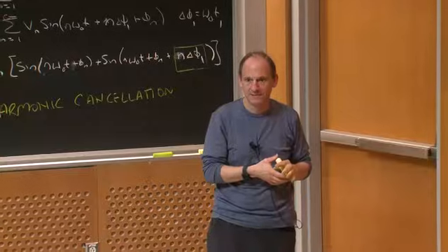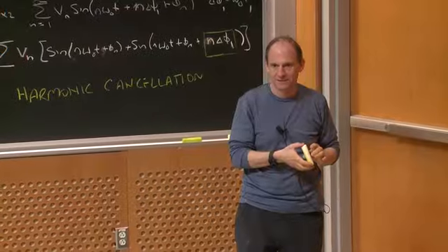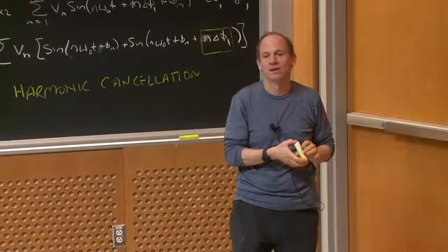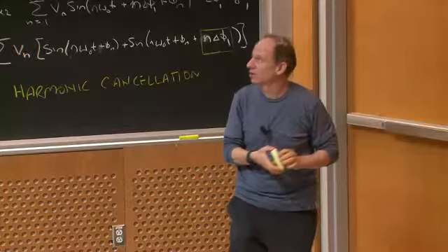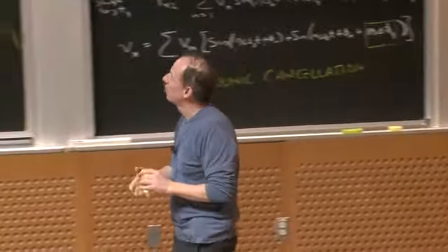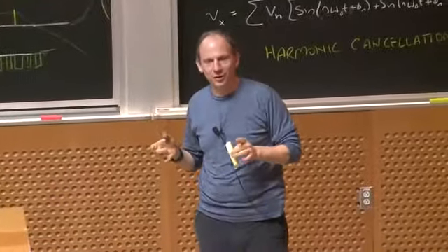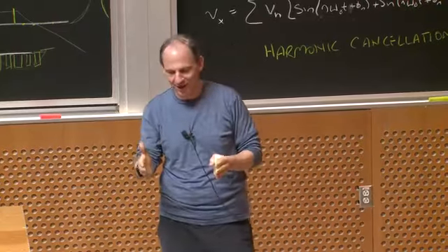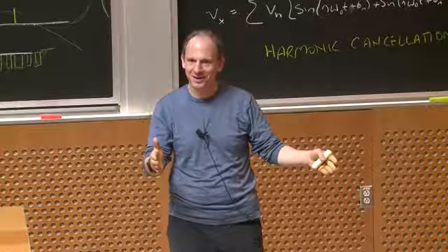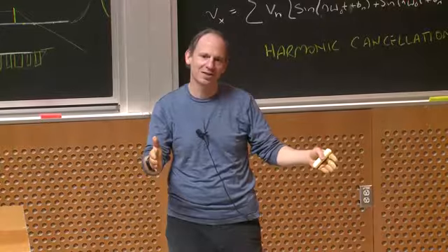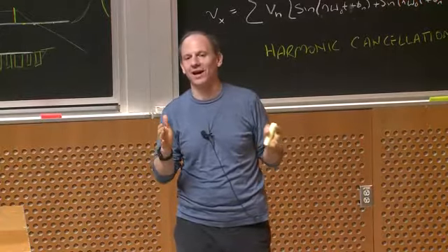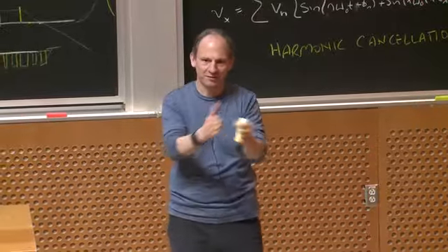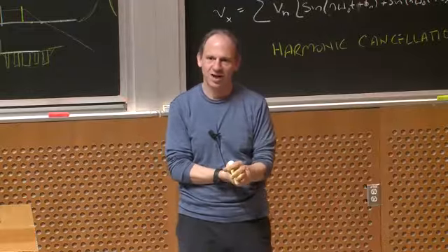Does the 6-degree displacement matter? Because it's a sine wave, but it's displaced by 6 degrees. Oh, yeah. Okay. So actually, if you look in the lecture notes, instead of displacing it by 36 degrees, I displace one by plus 18 and one by minus 18, and you get the same cancellation, and then it stays odd. So I don't have to have 0 plus a delay. I can have minus half the delay and plus half the delay, and it still stays as an odd waveform.